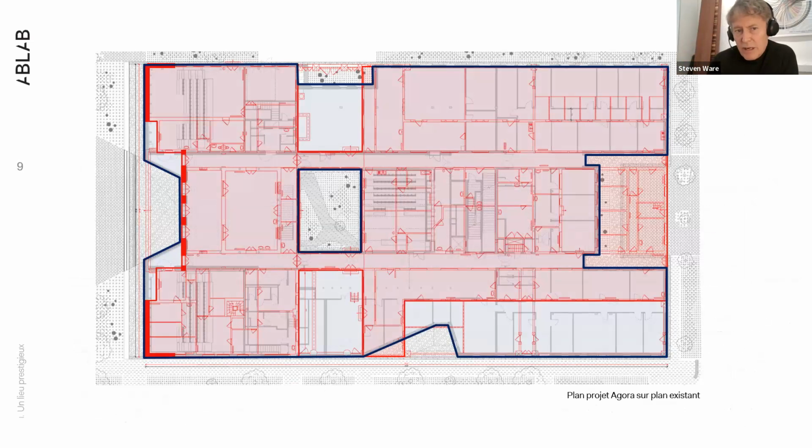So what we did was we took the building and we looked first of all at where the existing foundations were, and we thought, okay, if we can take this building as a material resource, perhaps we can go further than simply knocking things down, which is the cheapest thing, and then maybe keeping one or two bits and trying to stick them back onto a new building. We thought, first of all, we'll look at the foundations, see if we can build on the existing foundations. So even though we have a radically new program compared to what the old building did, we can actually maintain those foundations. And if we use timber construction, much, much lighter than concrete and steel, we can do a minimal amount of shoring up of those foundations in order to build the new building.